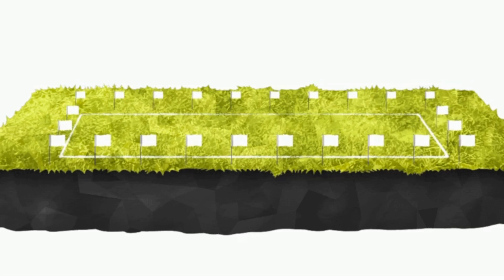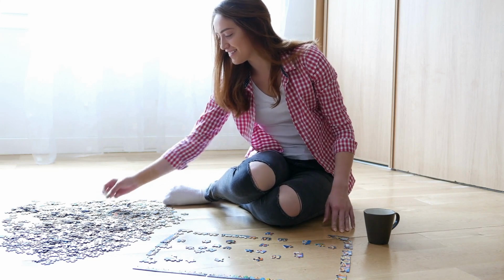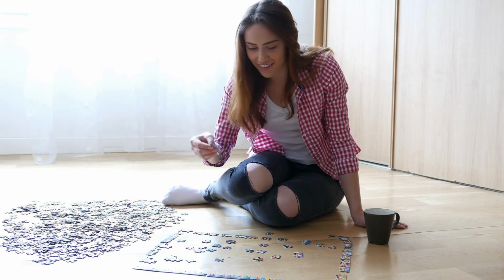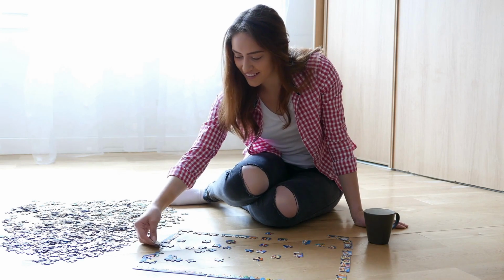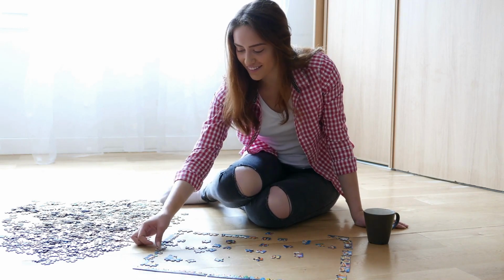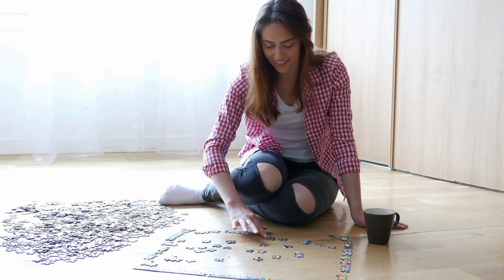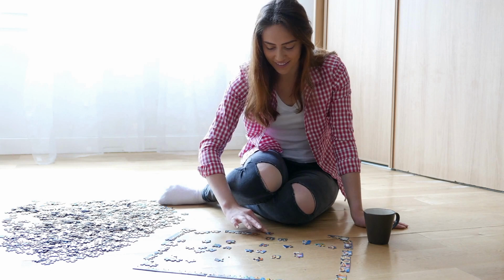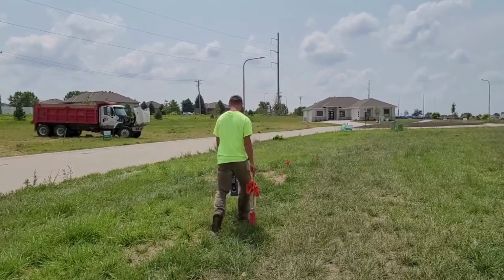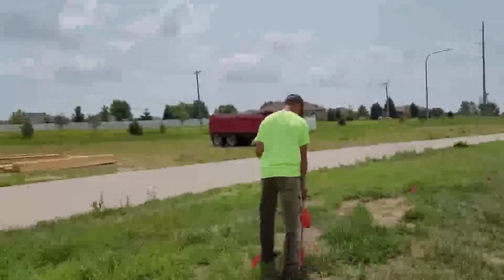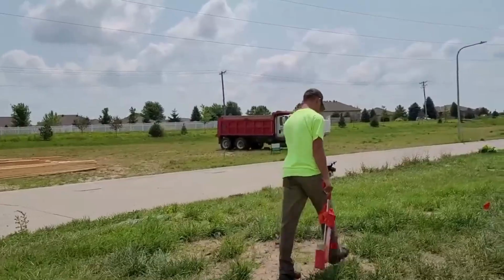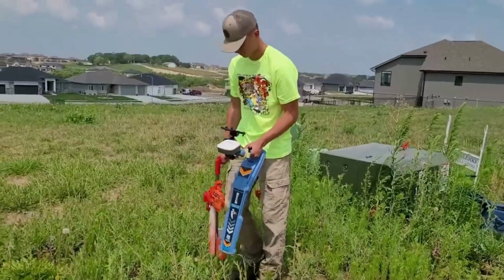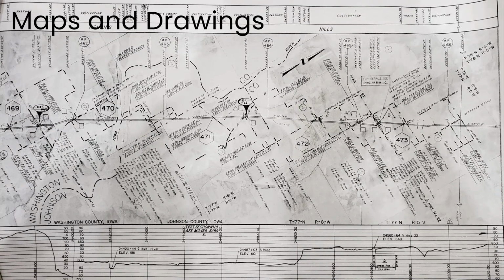And you also can compare that to the above ground features, all the landmarks that are around you, maybe the pedestals, the hydrants, the valves that you can hook onto to apply your signal onto the lines you need to get located. And so when you're doing a locate, it's like putting a puzzle together. You always start with the outside edges. You start in an isolated area and you go into the mass. You go into the congested area. Never try to start in the congested area because it's going to be much more difficult to identify and figure out which signal you should be following. Take the prints and then figure out where you need to hook up, apply your signal, receive your signal, get everything located out, verify your signal's good by your checks and balances, which we'll cover later, and then put your paint and your flags down.